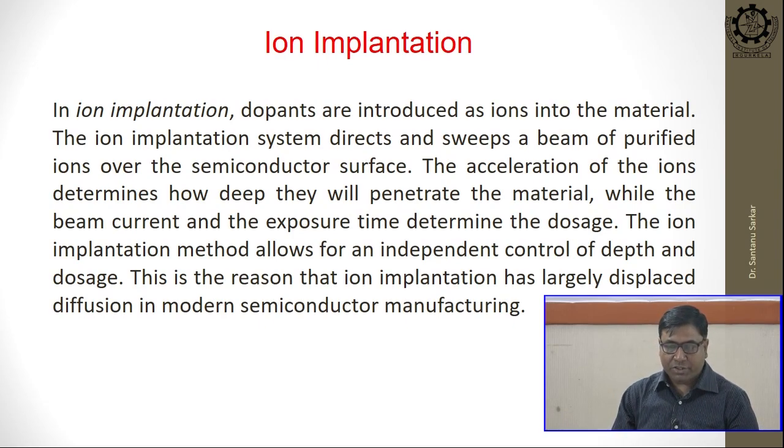Next procedure is ion implantation. In ion implantation, dopants are introduced as ions into the material. The ion implantation system directs and sweeps a beam of purified ions over the semiconductor surface. The acceleration of the ions determines how deep they will penetrate.